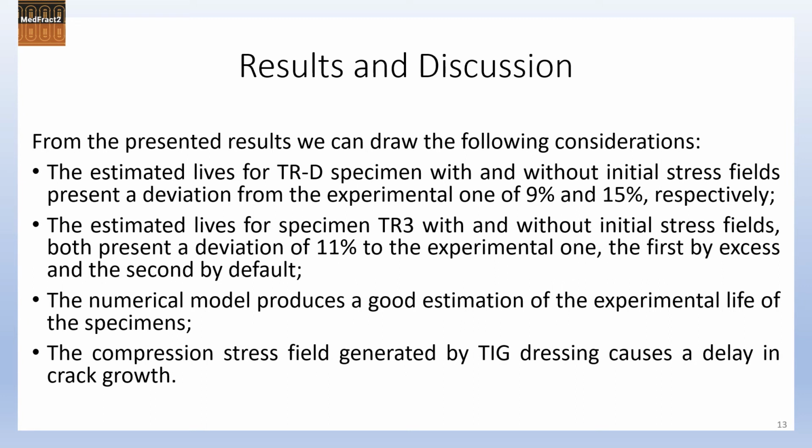The numerical model produces a good estimation of the experimental life of the specimens. The estimated geometry of the final configuration of the crack is close to that which occurs in the specimens. The compressive stress field generated by TIG dressing causes a delay in crack growth.